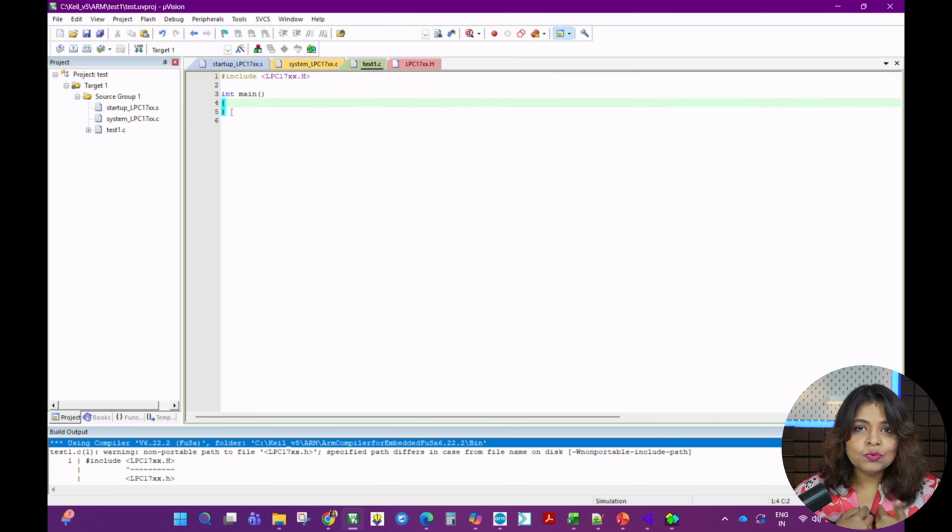Even if I write an assembly program, MOV A, 100 or MOV R0, 100, the processor will not understand because it needs opcodes. Again, the assembler will convert that assembly language to mnemonics or opcodes. So this is what a compiler or assembler does. You may think assembly language is a low-level language. True, but the instructions or mnemonics are still not understood by the processor. It only understands opcodes. So the job of a compiler, assembler, translator, or interpreter is to convert your high-level language to the opcode.